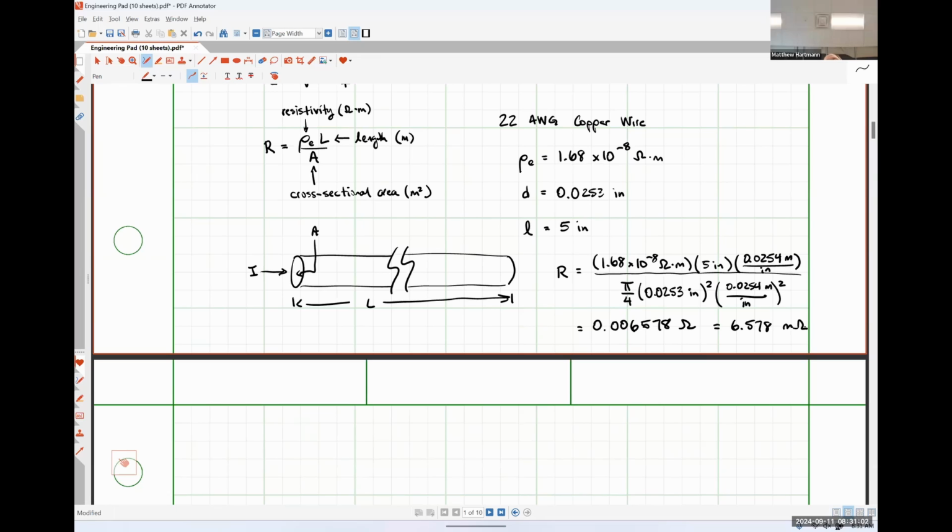So the reason why you were able to treat all of your wires as if they didn't have any resistance is because of this equation. As long as we don't make the wire incredibly long or have an incredibly small cross-sectional area, the wires don't really contribute a whole heck of a lot of resistance as compared to the size of the resistors that we use to create our circuits.